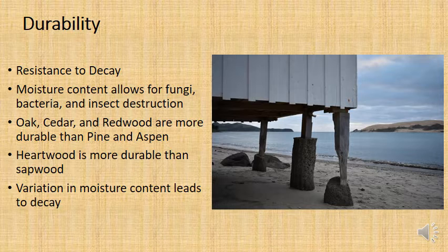And then the tide comes up again and the moisture content goes up. It goes up and down, up and down. That is shrinking and swelling the wood two times a day with the tide. And what has happened? Well, you can see there that the wood is slowly decaying and washing away. So that house is going to collapse unless someone replaces that stilt at some point. But that's one thing that can lead to decay.